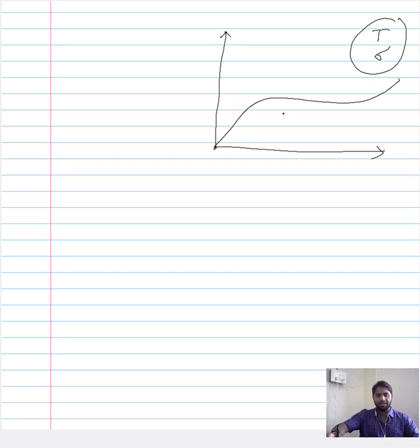So we saw there is an instantaneous creep stage where the creep rate is constant, and this happens at the very instant once you start applying the load. Once you start applying the constant load, or the constant stress, there is an immediate response from the material, and that we refer to as the instantaneous creep. And following the instantaneous creep, we have a decelerating creep or the transient region. In this region, the slope of the curve is decreasing, and this we refer to as the transient region or the decelerating creep.